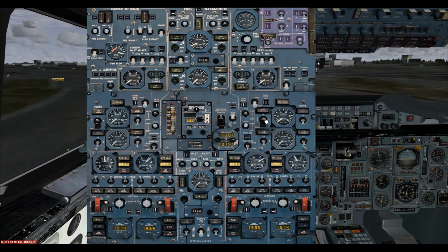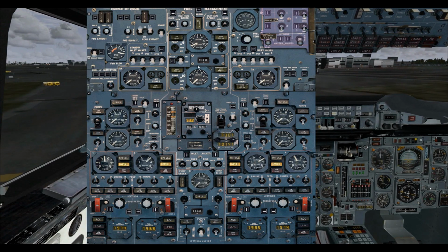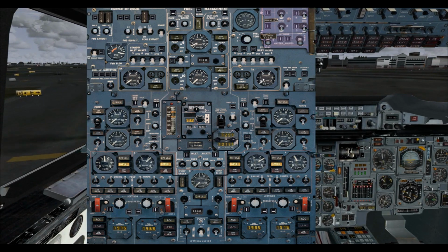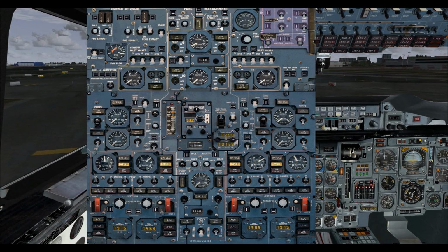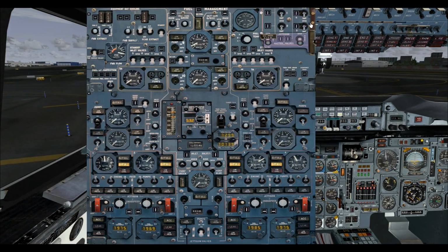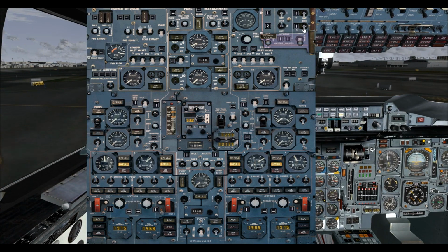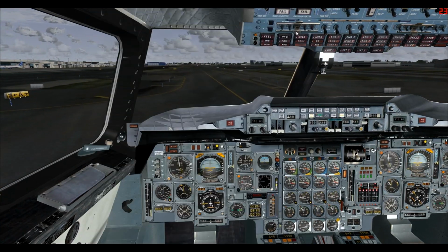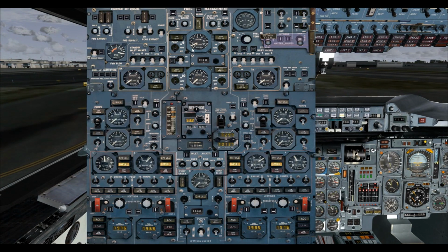And then what we're going to do is pump fuel from the remaining tanks into tank 9. So the way to do that is we open up our inlet on tank 9, the main inlets. Just going to look where I'm taxiing here. Then we're going to pump fuel from, let's say, 2 and 3 through the jettison system, and pump it into tank 9.